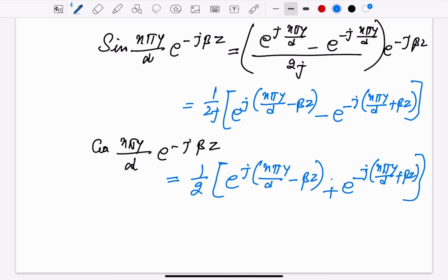So the lowest frequency for TE or TM mode, and we are aware that for both modes this frequency is the same, meaning the cutoff frequencies for both TE and TM are the same.